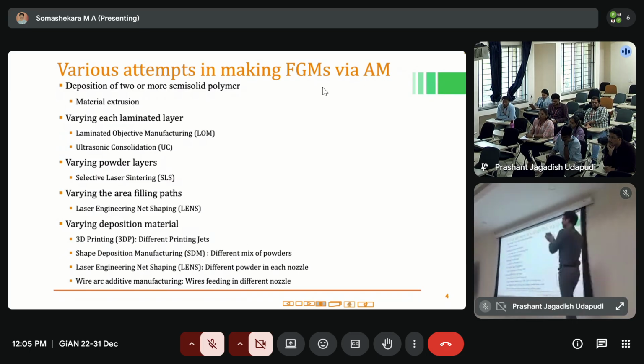For example, if I talk about this component, say this is 0 0 and this is x equals 100. At 100, right, which material should go and what composition should it be? Because you are controlling through your computer. You may be controlling it, but how much is effectively being deposited, that percentage of material, right? How will I know that 1% titanium and 99% other material is actually being deposited, so that you are transitioning into 100% material B?